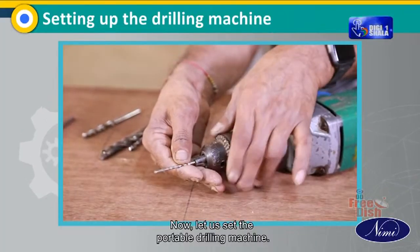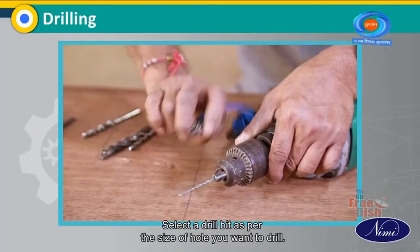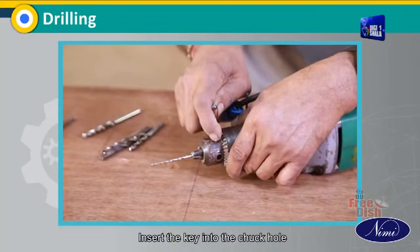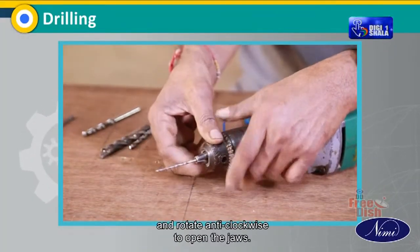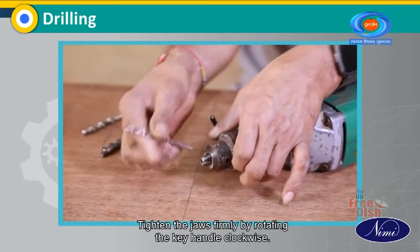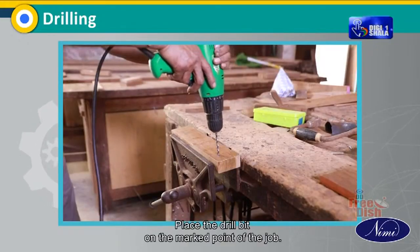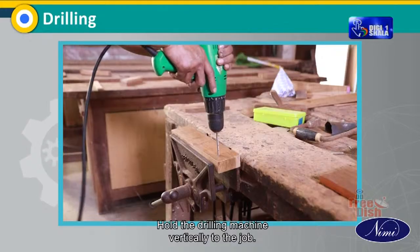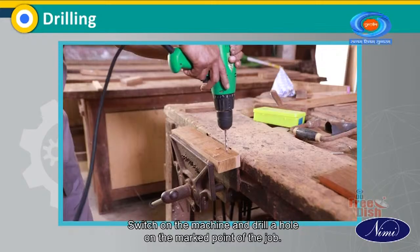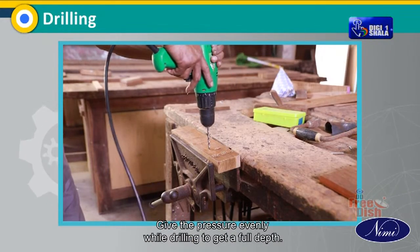Now, let us set the portable drilling machine. Drilling. Select a drill bit as per the size of the hole you want to drill. Insert the key into the chuck hole and rotate anti-clockwise to open the jaws. Tighten the jaws firmly by rotating the key handle clockwise. Place the drill bit on the marked point of the job. Hold the drilling machine vertically to the job. Switch on the machine and drill a hole on the marked point of the job. Give the pressure evenly while drilling to get a full depth.